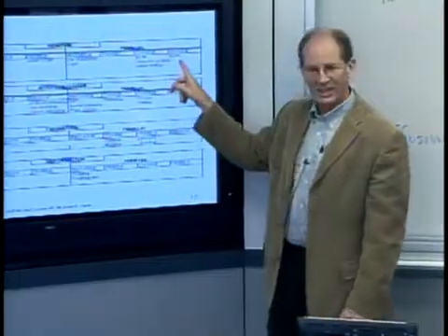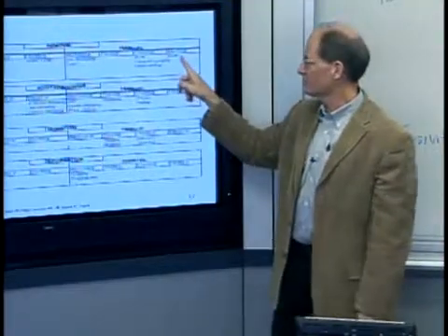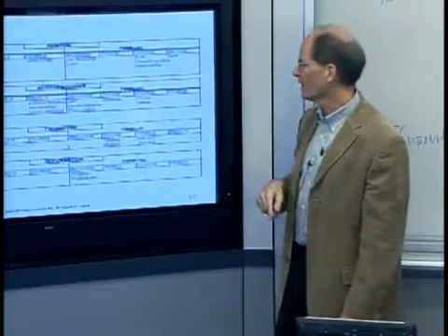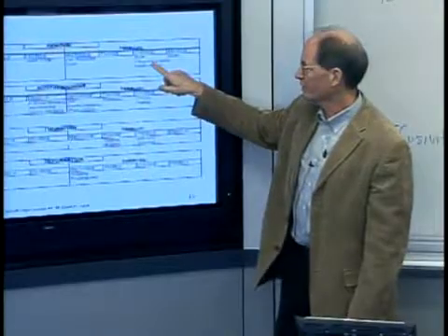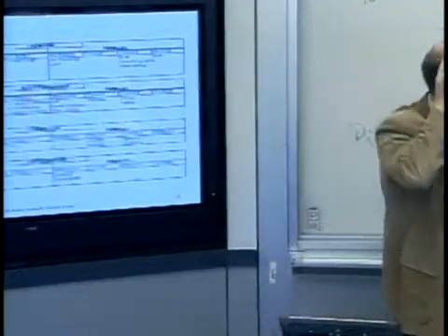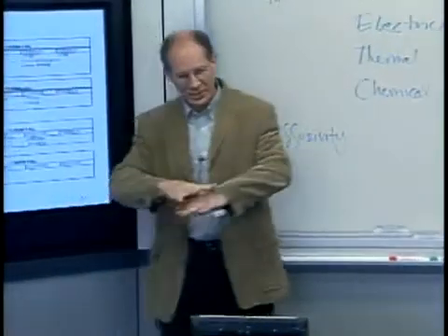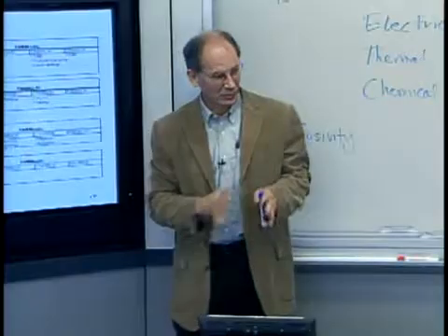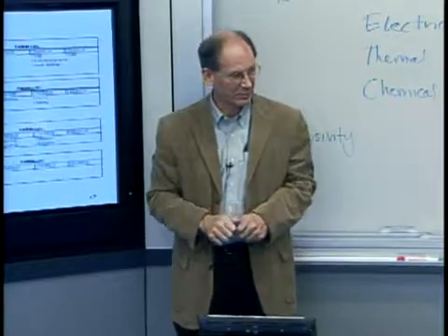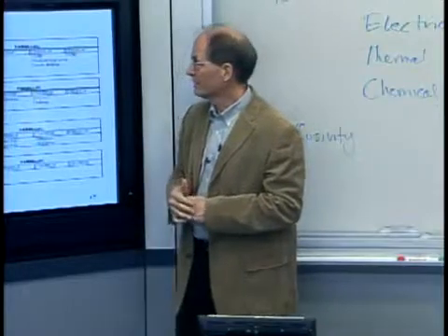Put a whole bunch of them together, do it all at once, say with a formed electrode. Now it's parallel EDM. Photolithography with a wet etch, if you want to think of it that way, is basically a parallel process. It's etching everywhere at once, but you just happen to put a mask in a few places. That's your tool, so that it can't etch, a resist.